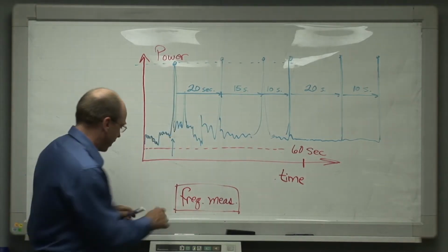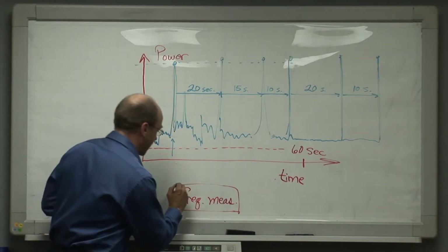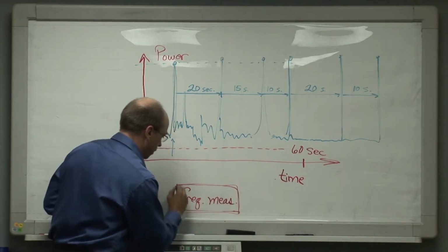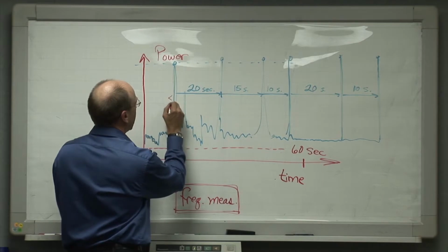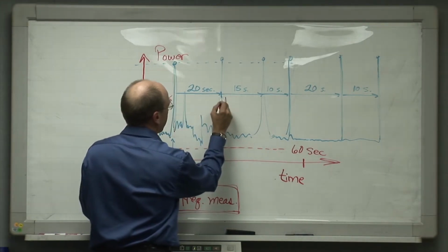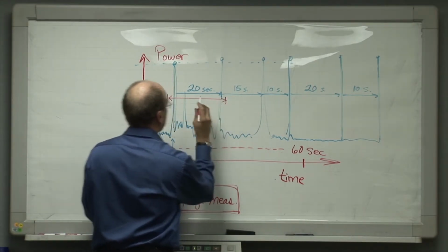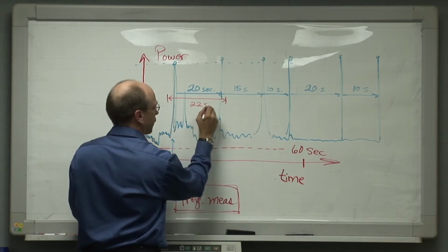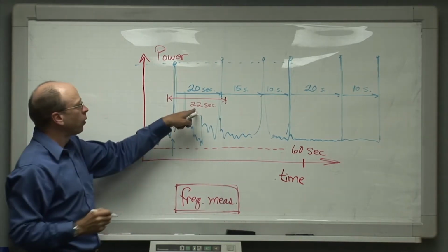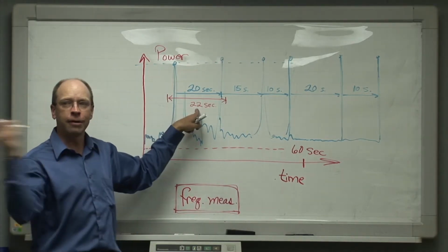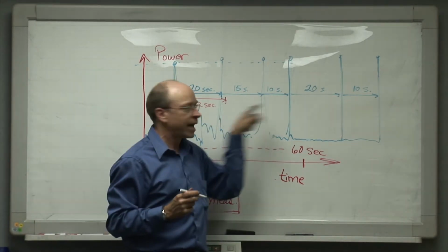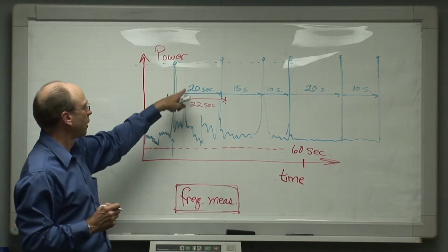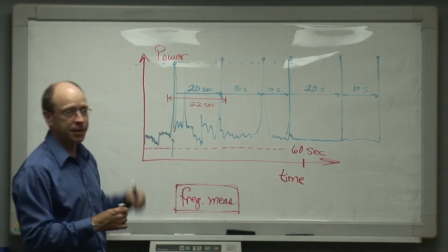If, for every measured frequency that we examine, we run the spectrum analyzer for an interval of time that's a little longer than 20 seconds, we'll say maybe 22 seconds for good measure, then we know that we'll always see the radar look in our direction within that interval. And if you don't believe me, watch the radar for 5 or 10 minutes and see if it ever goes for less than 20 seconds, or whatever that interval turns out to be for that radar.